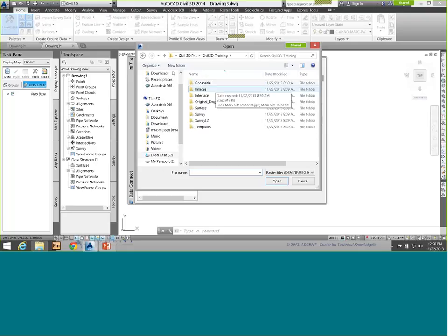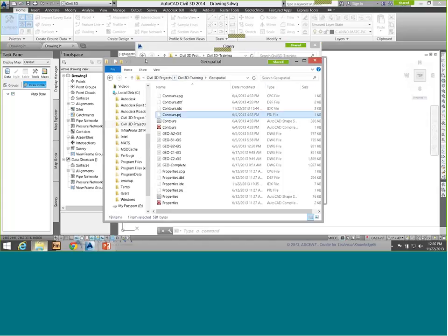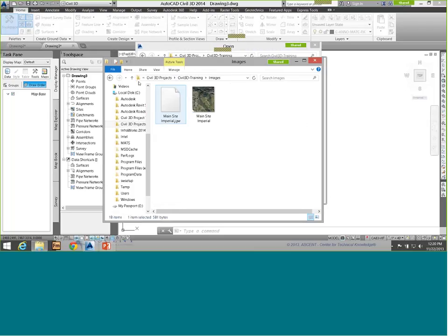And let me just quickly show you what I have available here. When I am connecting to my images, you'll notice that I have an image and I have a JGW file. That is a world file. You want to make sure that you have that, because if it recognizes the file that you have, you won't have to manually go in and set the coordinate system. You can just have it automatically assign it.